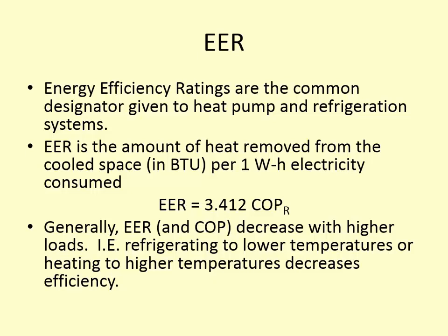So the energy efficiency rating is a measure of how well your heat pump can remove heat from a cooled space, and it's in BTUs per 1 watt-hour of electricity. And there's a conversion between EER and coefficient of performance. So if you're given an EER, you could calculate your coefficient of performance using the manual.